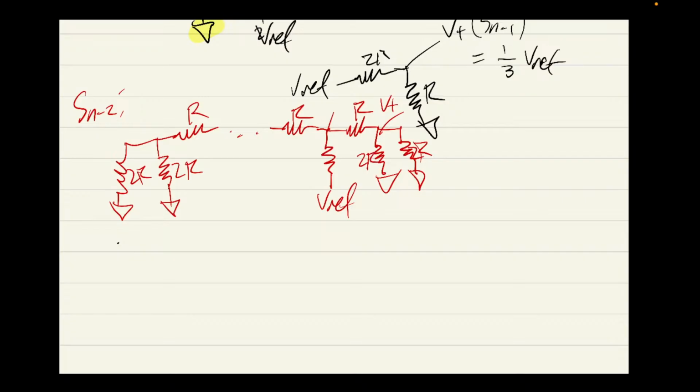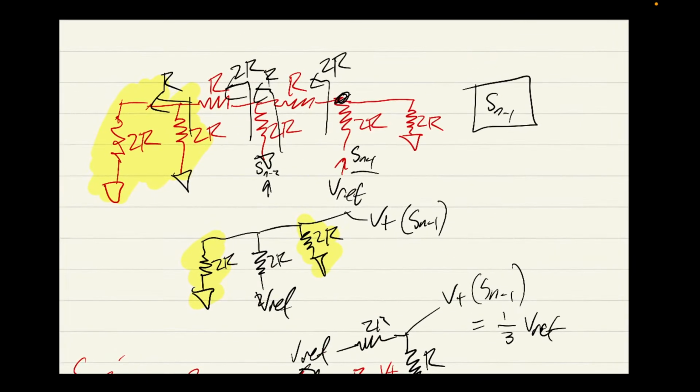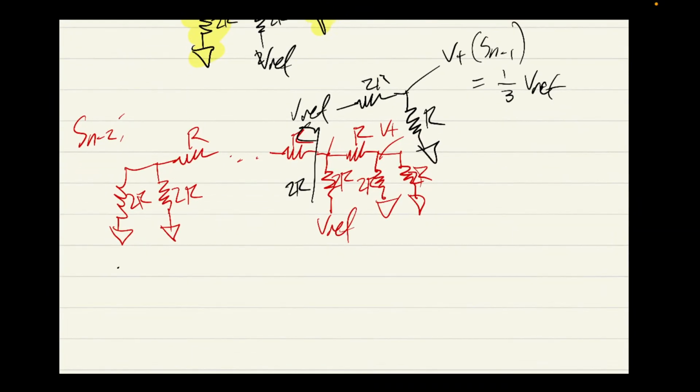2R, 2R, 2R, and we should be good. All right. Now, understanding from previously, we know that looking left from over here, we end up with 2R on that side. Same working out as we saw previously. If we cut it just before the node, we get 2R. If we cut it just after the node, we get just R as the equivalent resistance looking to the left, okay? So if we run that back, we end up with another simplified circuit, all right?